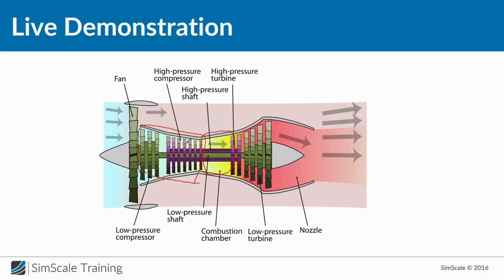And this compressor stage is in the end made of rotors and stators. And the rotating blades add energy to the fluid, which will increase pressure and temperature. Just to give you an example, inlet temperature is about 10 degrees Celsius, and the temperature for the combustion chamber is around 450 degrees and around 35 bar pressure. Great, okay.